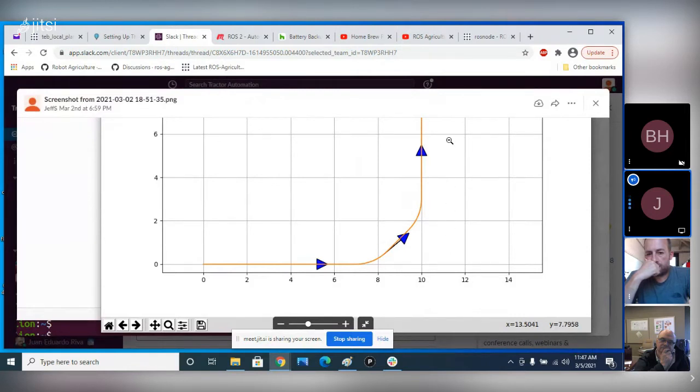And the vertical line will not be on the one where we told it to be. It will not be on the line that's at 10. It'll be on a line that's actually out at 12. So if you drove all the way to 10, it would draw an arc out here to 12, and put a line that we did not specify, but it will be 2 meters over because that's what the radius says. So this trick, you say, if I'm at 0 and I want to go to 10, I stop early.